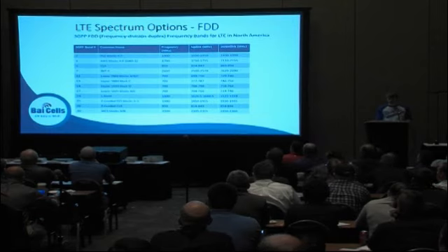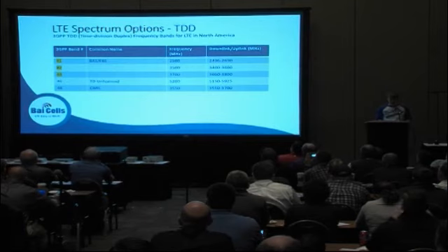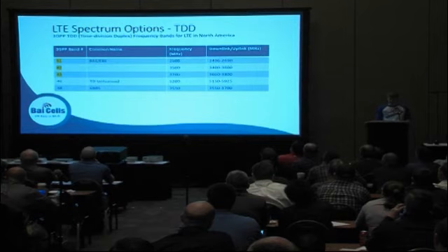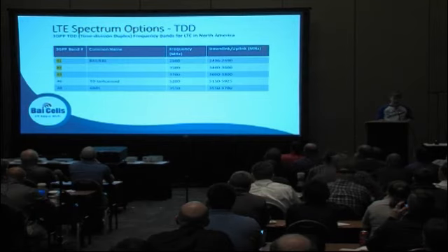Right. And then we have the TDD bands, and I highlighted in yellow the main ones here. So pretty much most operators will have the 3.65 license, I'm assuming, and that's our main sale, our 1 watt eNode B, which is band 42 and 43. So we call it two different bands because the CBRS band falls in between those two bands.